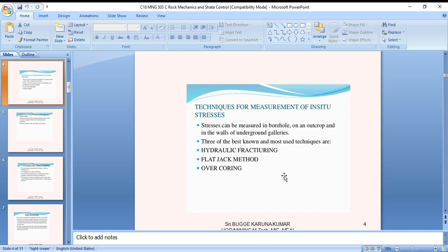Many of the rock mechanics instruments reported in the literature were built to operate in a specific environment under special circumstances. The engineer should be cautious using many of these instruments in a different environment under other operating conditions without first calibrating or otherwise checking them under the intended service condition.